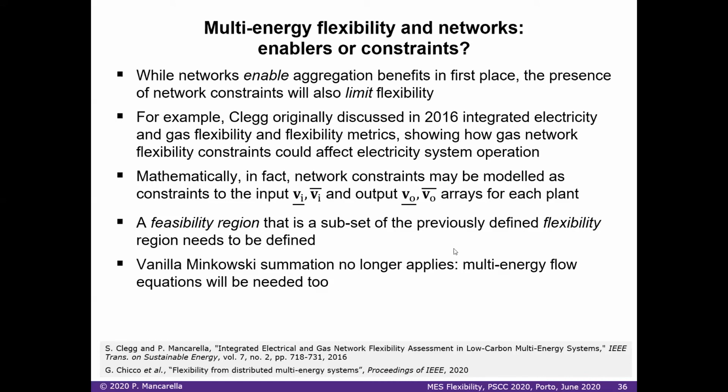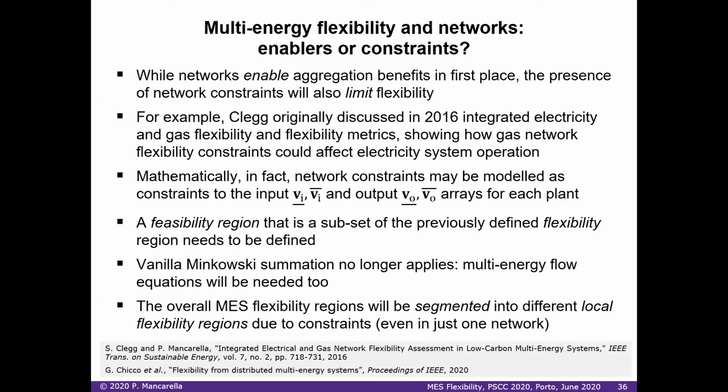The most important thing is that mathematically, you cannot just apply this vanilla summation or Minkowski summation. You now really need to build these flexibility maps by multi-energy flow equations, the likes that Alex introduced before, and the likes that you will see with Misha and Vittorio this afternoon. And also, once you have networks and network constraints, you start having segmented flexibility regions.